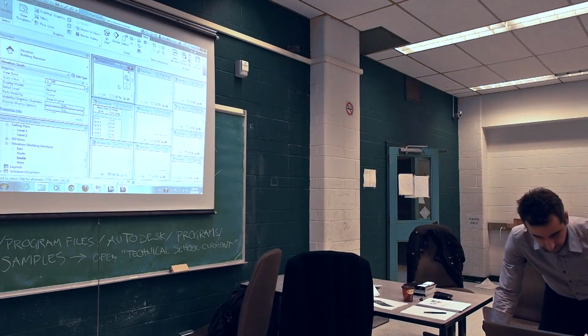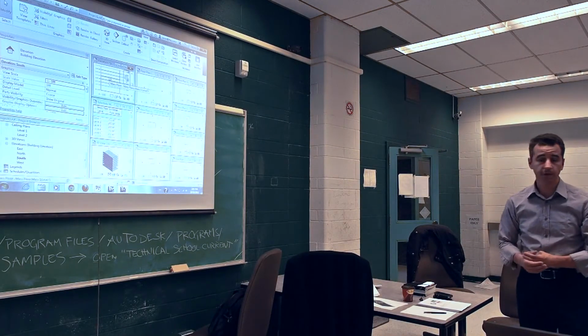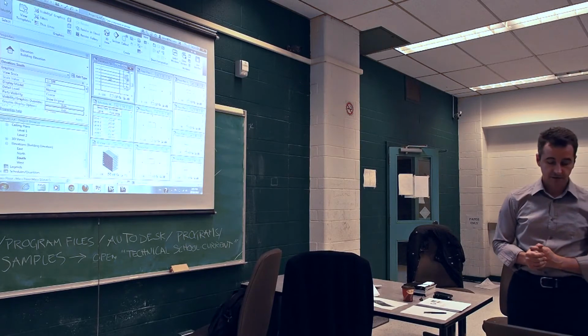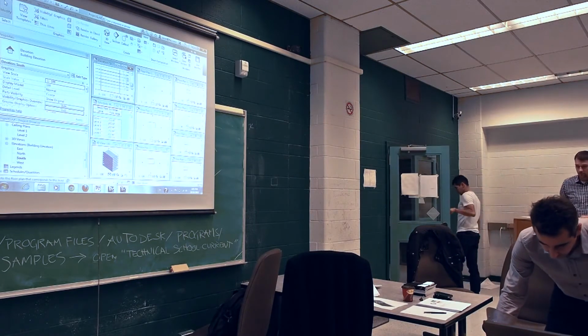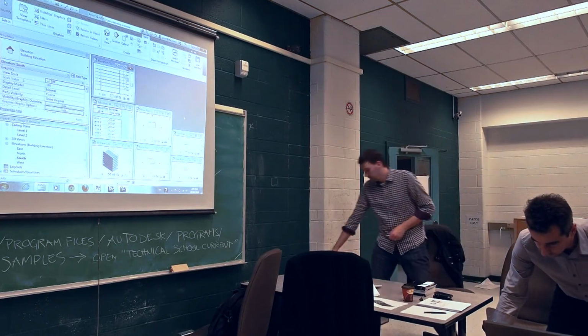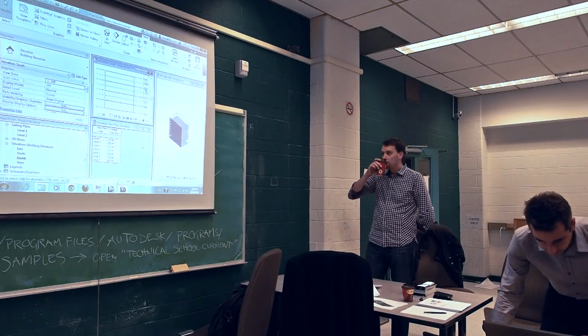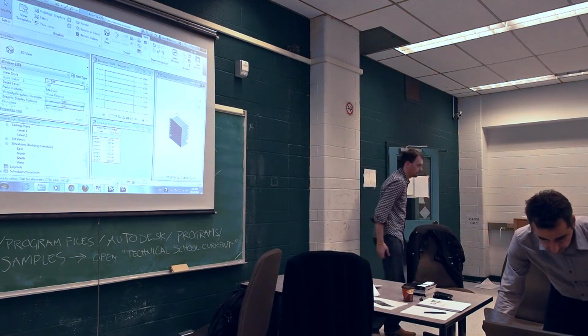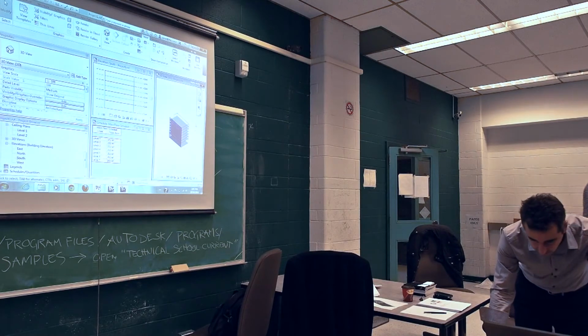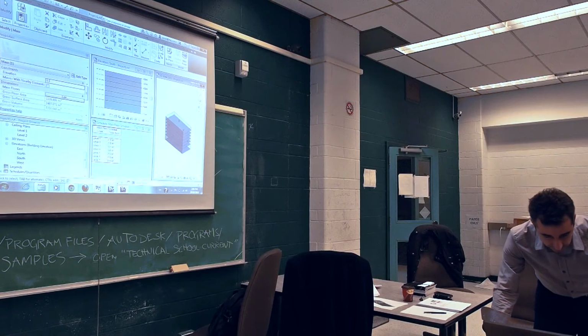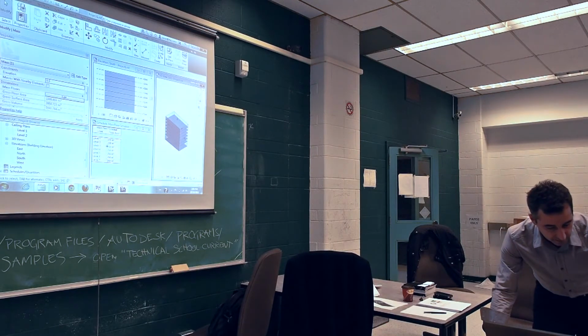WT is a shortcut, and it's used for window tile. Every single window open is going to be tiled in here. ZE is another shortcut that stands for zoom all in all open views. So I got a little bit excited here and just closed these down or minimized them, and then WT again, so I get more real estate. What do I see here? So I have all the levels and all the square footages, and if I decide to change my object, I don't know if you noticed, but this number changed, right? So if I decide to change the footprint, the schedules are updated.